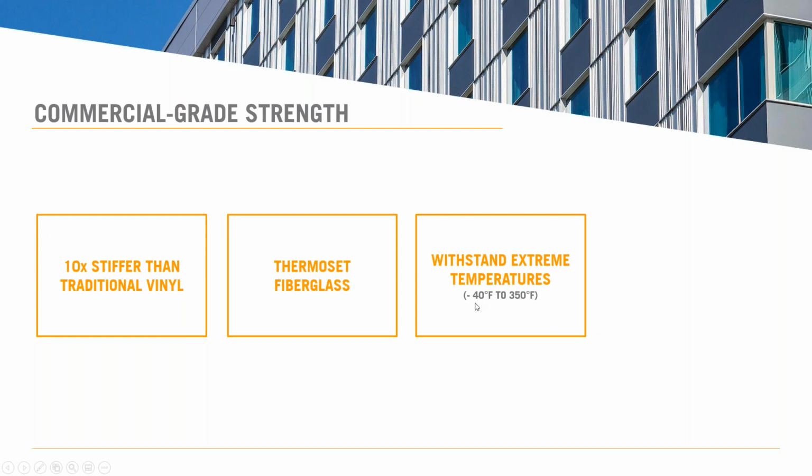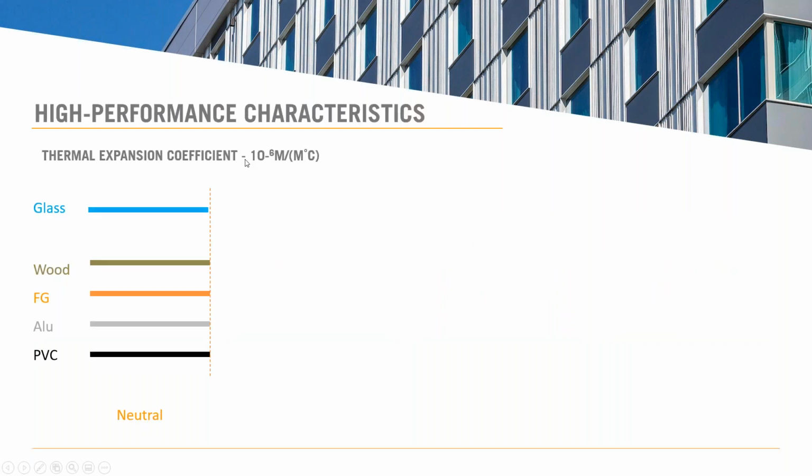So one of the reasons you see fiberglass selected for northern applications or extreme heat and extreme cold is it's very resistant to temperature fluctuations. And of course, it's extremely durable because you can't really unfry the egg, so to speak. It's a very durable material that has a modeled lifespan exceeding 50 years, which plays into the energy efficiency.